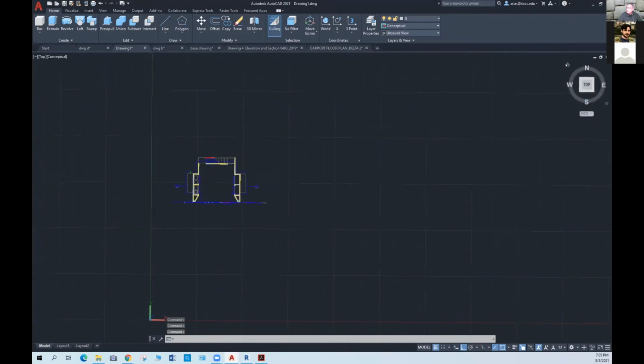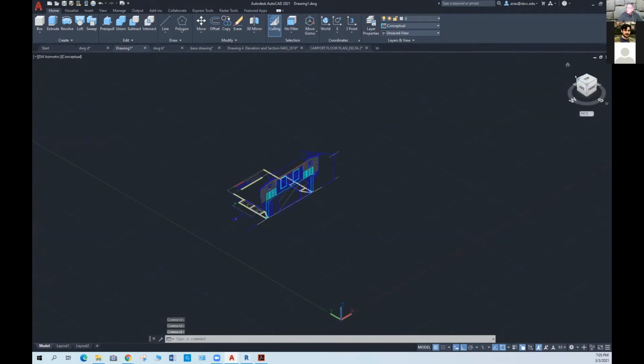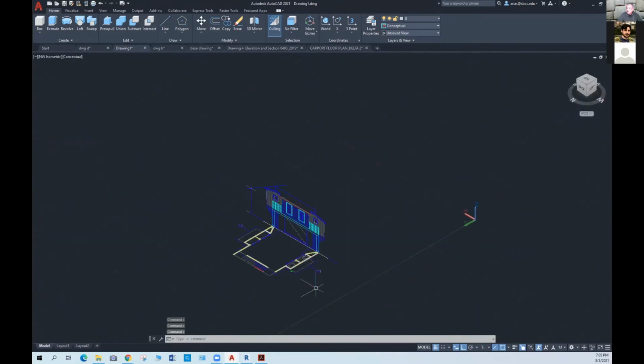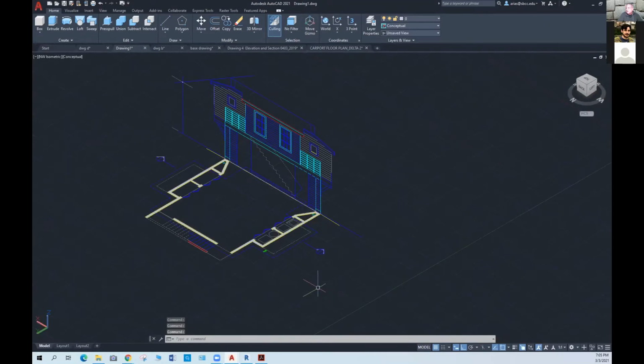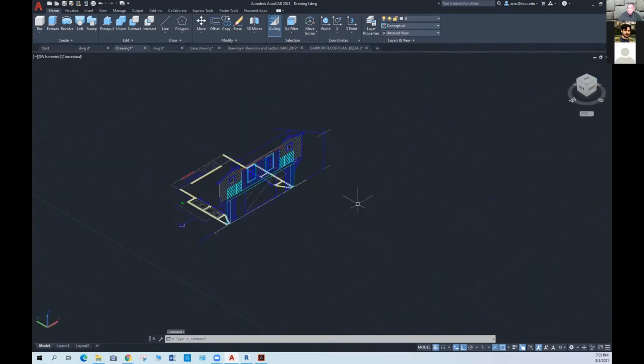And we achieve that by manipulating the UCS as needed to create the views that we want. Now, again, if you have drawn the floor elevations of your object, you can bring the floor elevations to match the sides of the floor plan and then create the geometry from there. And so that's what the UCS allows us to do, is to control the work plane that we use in the program.